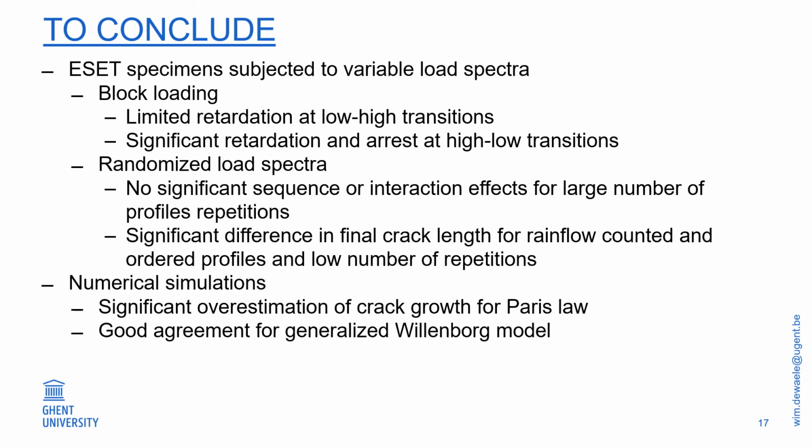However, for the Rainflow counted spectrum or spectra, we saw a lot of crack growth retardation. We also performed some numerical simulations which showed very significant overestimation using the conventional Paris law and allowed good agreement while applying the generalized Willenborg model.